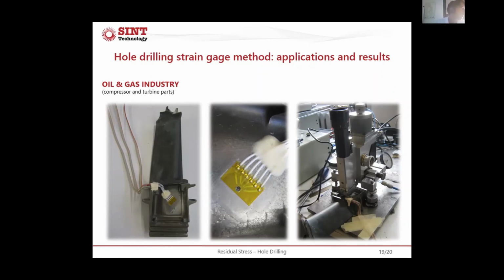Shot peening, probably you know, is something that you introduce into the material if we want to add a compressive layer, valid in particular for the components that will be subjected to tensile stress during the lifetime in operation, in order to balance the tensile stress as an external load with the residual stress. In this case, we want to add compressive residual stresses. And this is a typical application.